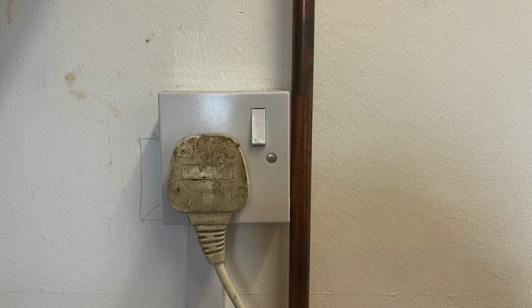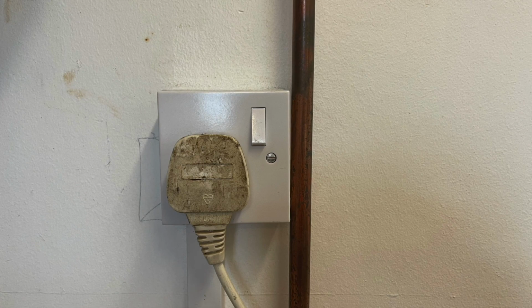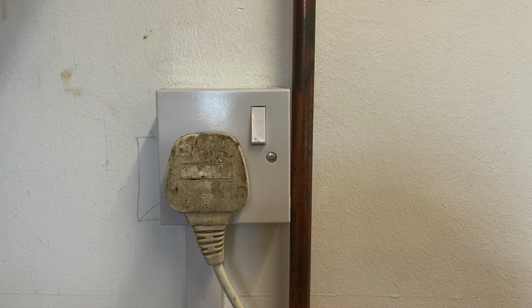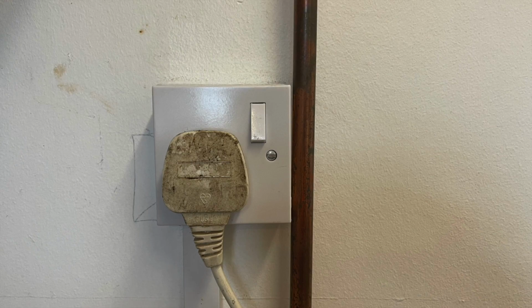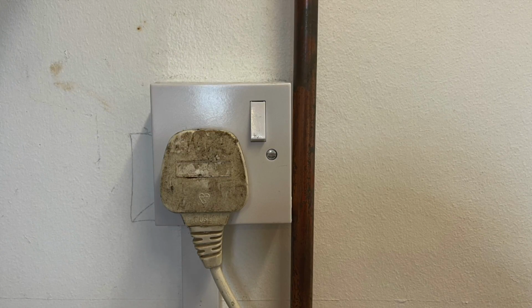Now this picture represents you going to do a landlord's report, and when you're doing your visual inspection of your pipework, you find this gas pipe is installed right next to a plug socket. So what would we categorise this as? Now, looking through IGEM G11, you won't find this scenario anywhere. So if you can't find the scenario in here, then basically you can class it as not to current standards. So how far does a gas pipe need to be away from a plug socket? Well, it's 25mm away from a plug socket or an electric cable, or 150mm away from a consumer unit.